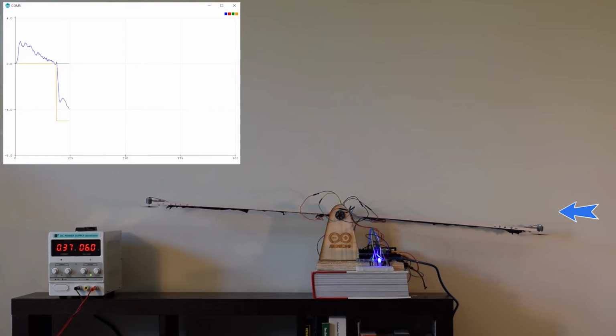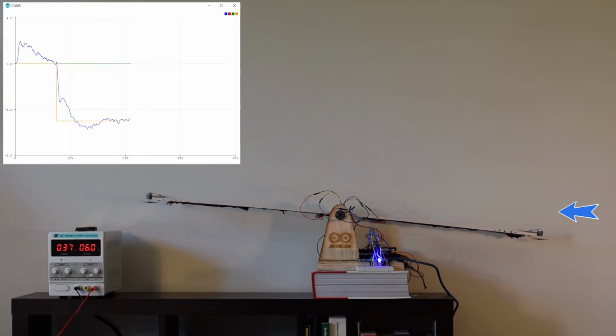The orange line represents the angle's set point, and the blue line is the angle value recorded by the gyroscope. On startup, the inertia of the motors caused a slight rotation of the system. The code was able to vary the PWM signal to the motors and correct the error caused by the inertia. I experimented with reversing motor directions to try and counterbalance the inertia. However, I was unable to totally eliminate the problem.